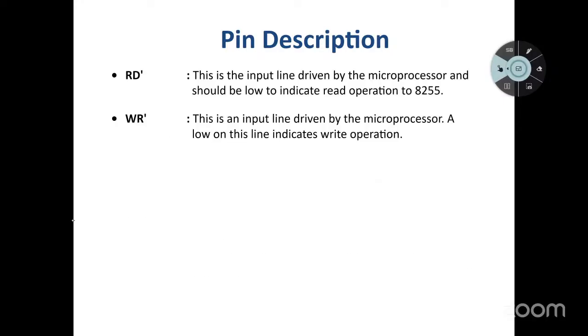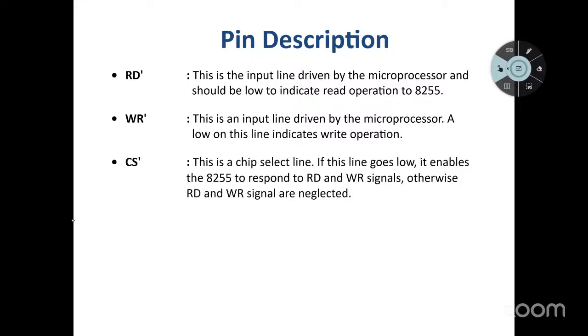This is the input line driven by the microprocessor, and it indicates the read operation. Read bar should be low because of the write signal. Here, this is a chip select pin. If this pin goes low, it enables the 8255 to respond.